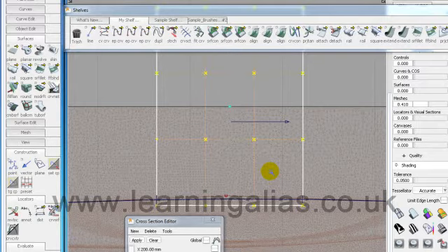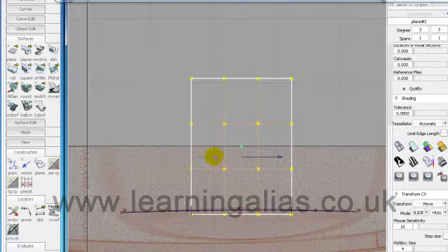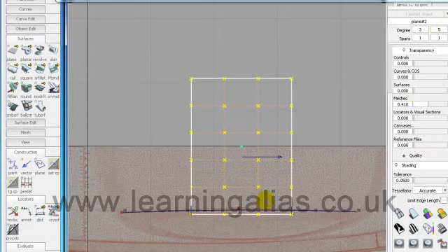We haven't got many CVs to work with, and probably, because we've got variation in the roof here, we're not going to get down to the mesh with those two hulls. We're not going to have enough. If we bring this hull down here, slide it, we're going to have a flat spot in the middle which we can't control. So we need more degrees. You can see here that it's the V direction, so come over to Control Panel, U, V, and up that to degree 5 and hit the space bar.